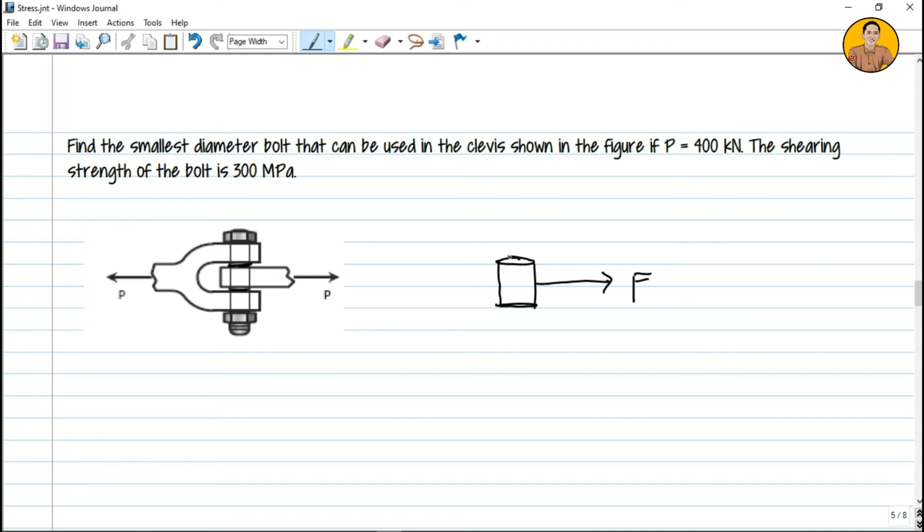Okay? Kunin natin yung portion na yon wherein doon na-apply yung shearing stress. Yung force natin. Ito yung area wherein pwede siyang magkaroon ng shearing stress. Ito, this is the parallel area. Okay, so dalawa yung area. So this bolt here is undergoing double shear. Double shear, bakit? Because if you apply a force here, yung area that is under shear stress, pwede siyang mag-fail in this portion considering the shear stress. So dalawa yung area under shearing stress. So therefore, if the area of this is A, A yung area ng top, A din yung area ng bottom.